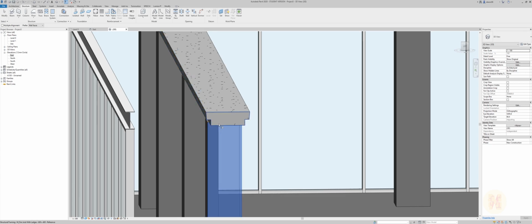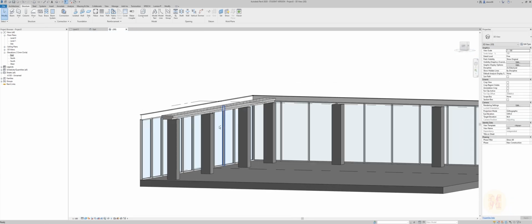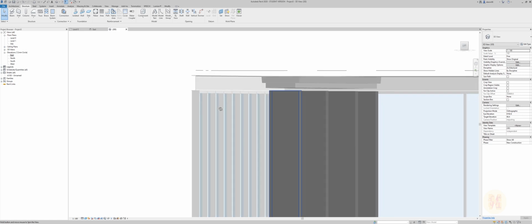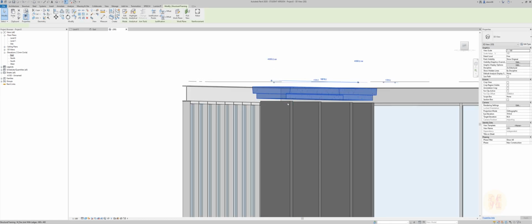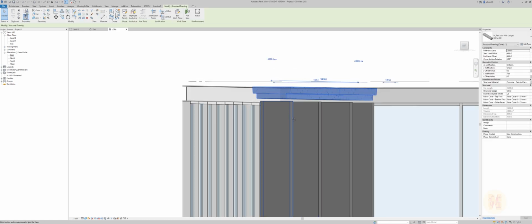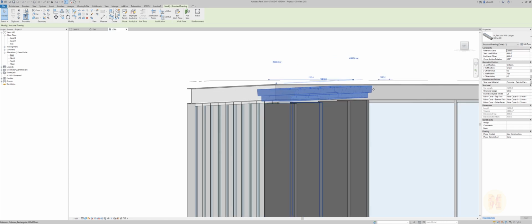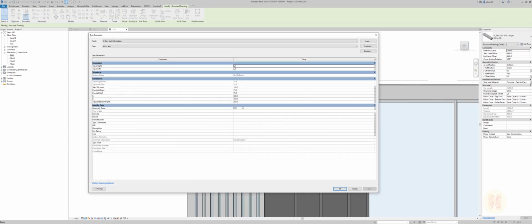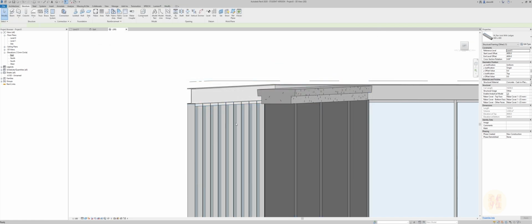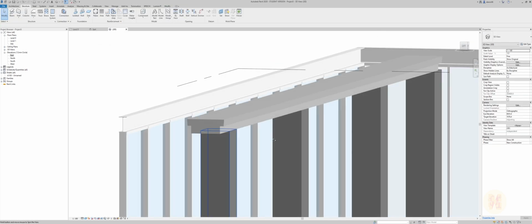Let's check it out. We will do like that, and as you can see, this size is the same. And now we should change the thickness, the height of my beam. Let's do the same thing. Let's find where this dimension is. Okay, this H, as you can see here. Let's make 400 millimeters. Let's say okay, and as you can see, it's exactly this beam.